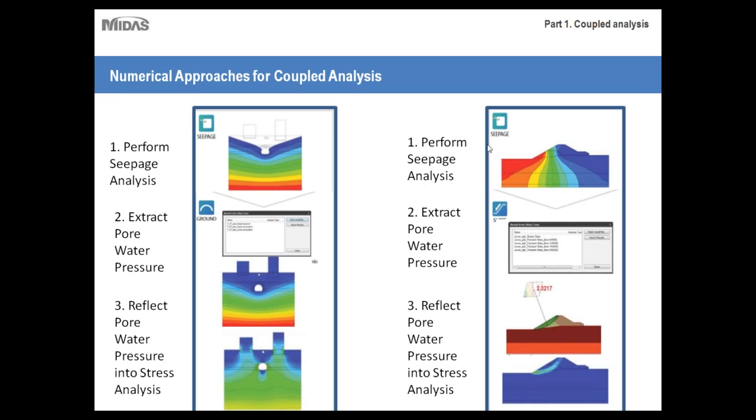So here we have another similar embankment type problem. Because there's water on this side of the embankment, the head is maximum at this side, and it's minimum at this side, and you'll experience a significant amount of seepage on this side of the embankment. So what you would do is, using the program, run your seepage analysis, get your pore water pressure loads, and then import them directly into your slope stability analysis. So you wouldn't even have to change your model file. Whereas if you had a spreadsheet, or were doing them by hand, you'd have to go from one analysis to another, and depending on the scope or size of your project, you could lose a significant amount of time, or you'd have to invest a significant amount of effort just into doing that transition.